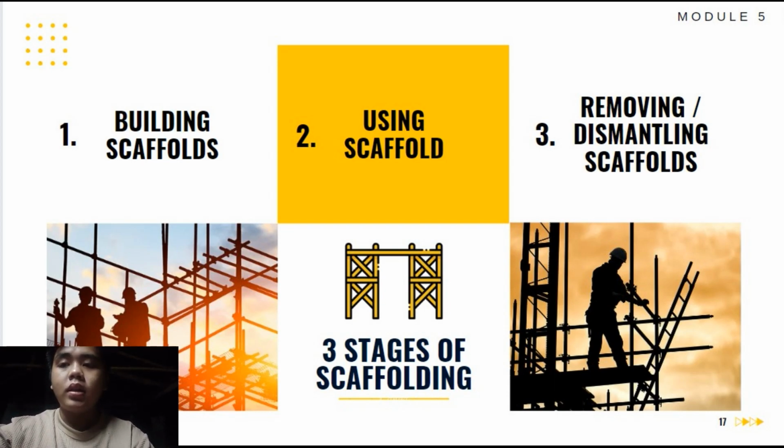The next one, access: no access by cross brace. When using ladders, the bottom rung should be no more than 24 inches in height. Can use side frames. Can access from another scaffold structure or hoist.